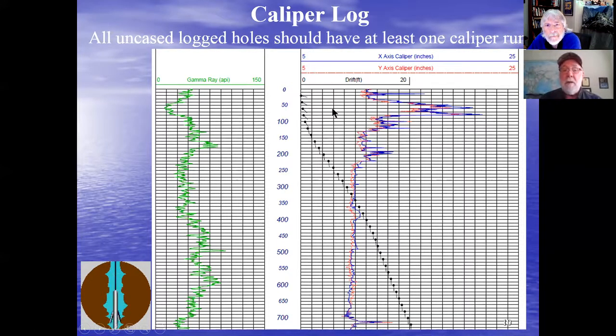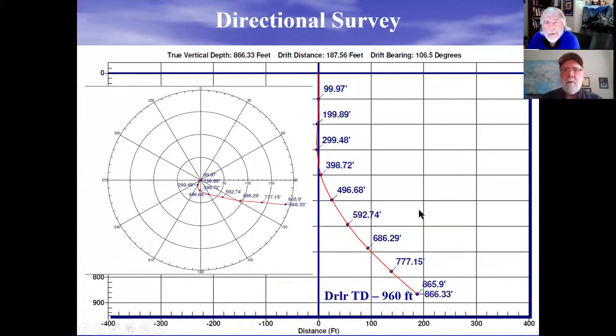The other thing that's shown here is a drift of the borehole. And I'll give you an example: all boreholes are normally assumed to be straight, which is a fallacy. This happens to be deviated as much as 20 feet down at TD near 725 feet. So next, there's even more on directional.